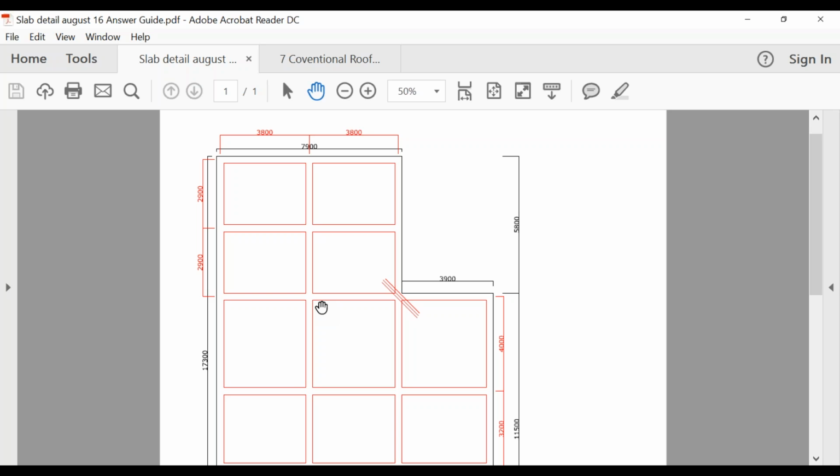Interestingly enough, yes, there was one, that little nudge out was 450. However, I thought it was a fireplace, and if it's brick all the way up, a fireplace tends to be a lot more weight there. But what I ended up doing was I just ran them across. Even with four meter centers, there were so many internal corners. We had to draw all the re-entrant bars, and I think there were 8 re-entrant bars we had to draw. It just jig-jogged all over the place.